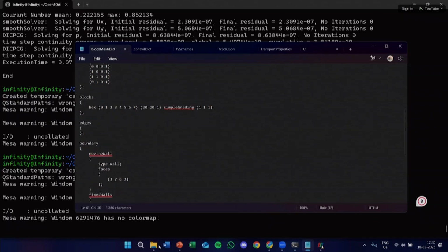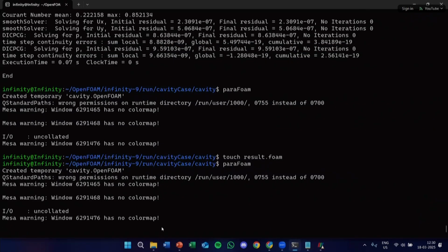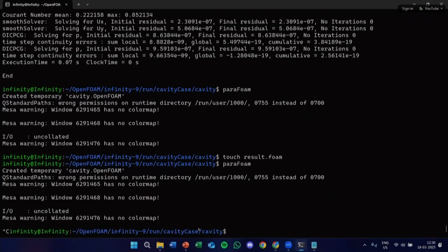Okay, it's giving an IO problem. So when you're typing blockMesh, it gives that error. Yes, blockMesh and icoFoam, both of them. Okay, just do foamCleanCase. Type this command, foamCleanCase. This will clean the whole case. If any previous data was written in it, it removes that. Now type blockMesh and see. Fine, I'll check it, sir.